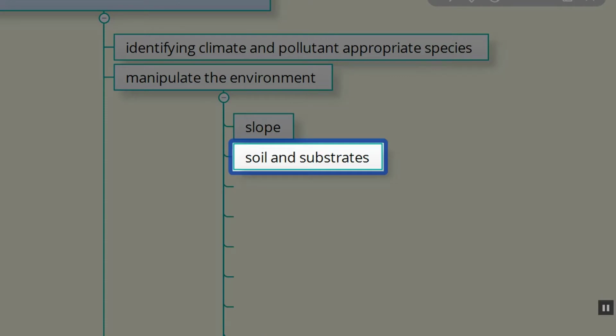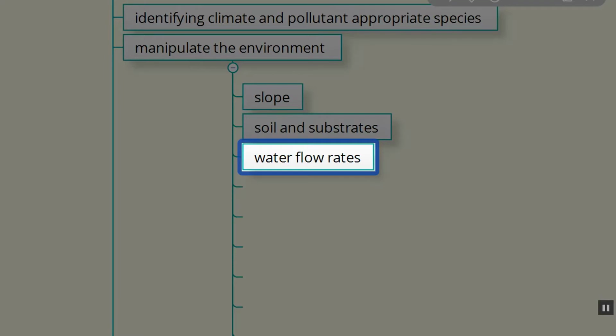So what about the soils and substrates? We need to know, do we have predominantly clay or do we have mostly gravel? On our site we have a lot of gravel, so that has tremendous porosity and water can go through that rapidly. So we need to be aware of that. We can easily get fluid into the aquifer on a site like ours. Whereas in a heavily clay site, it's going to create more of a barrier for those pollutants to get into the aquifer. So realizing what we're dealing with on site.